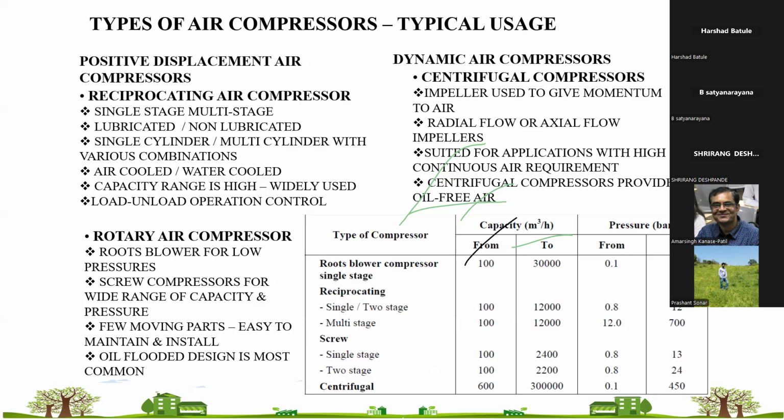In compressor technology, we have inverter compressors or similar technology. No, that entire HVAC part is different compressors. They are used for your chilling and cooling applications. These air compressors are different compressors. Considering the power consumption, can we have an option of VFD connectivity? Yes, variable drives are there. Whatever you are saying, inverter based, those terminologies are for your split ACs or VRV kind of thing. Variable refrigerants are used. So these are the major differences.